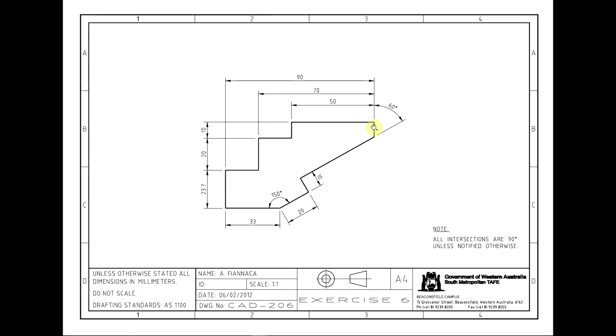this corner. The reason I'm choosing to start there is because if we have a look, we really don't know this length here. Now, a lot of people will assume it's the 10 millimeters that we see over here. It's actually not. We're just looking at this measurement here. The drawing doesn't actually give us the measurement. We also don't know this length here, so the easiest way to start, considering we know lengths and heights for all the rest of it, we'll start up at this point and we'll work our way around until we get to this point. So you can see these lines, they are all straight lines.